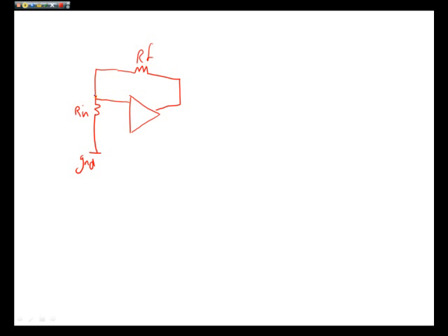Okay, looking something like that. So that's our negative gain. Now we need to think about what our positive feedback fraction is going to look like. Our positive terminal has a resistor and a capacitor down to ground, and also it has a resistor and a capacitor in series to the output.